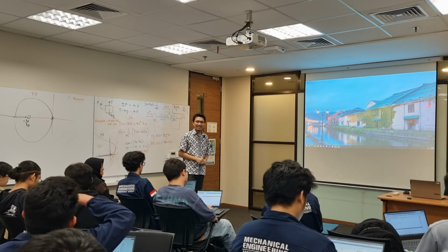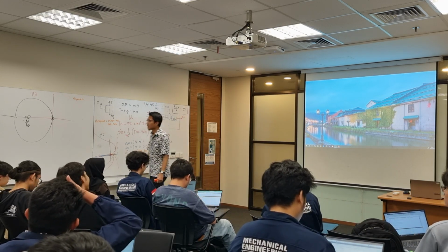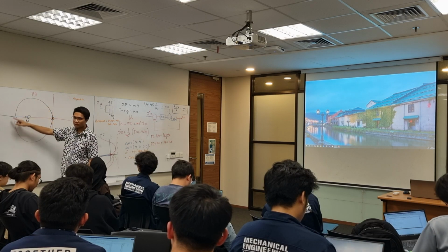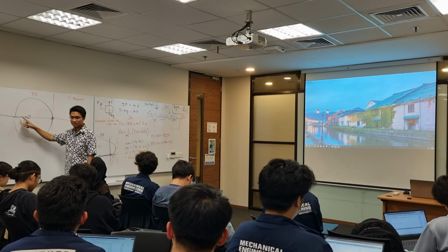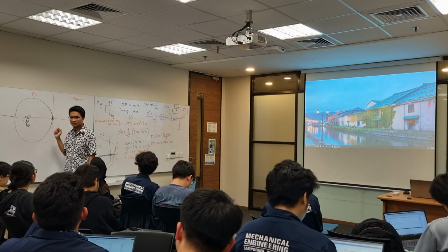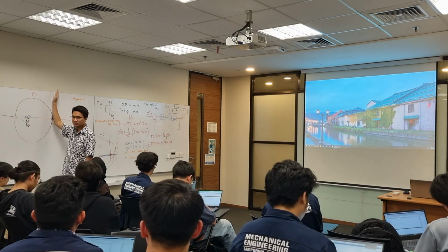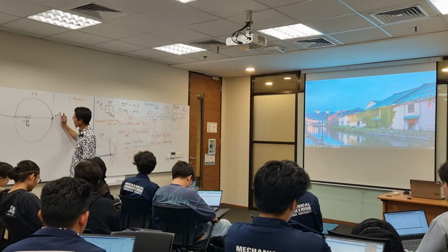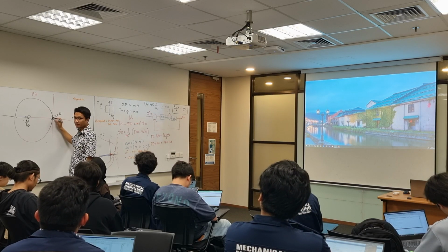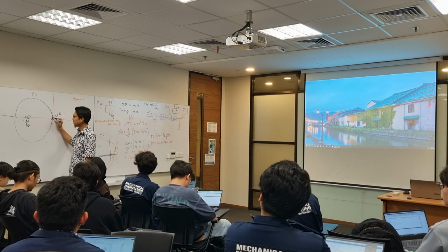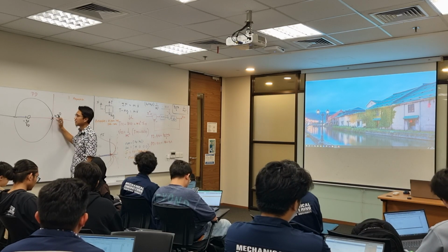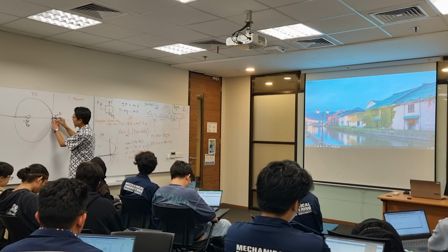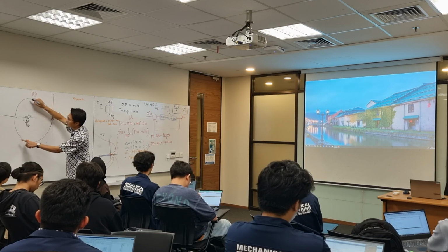So, what does the circle mean? This is the location of your closed loop poles. The poles are valid and stable if it is on the left. In here is when you set your gain to be 0, both of them 0. It is here. Open loop. The closed loop pole, when you set your K to be 0, is here. As you increase your K, they will go following this path.